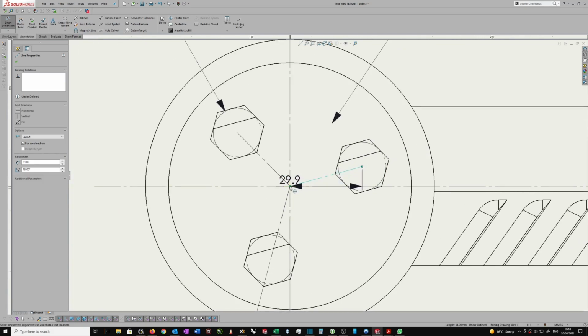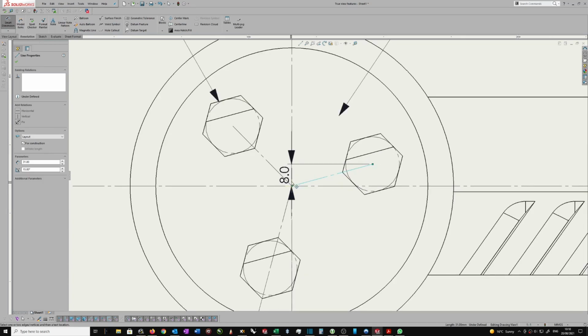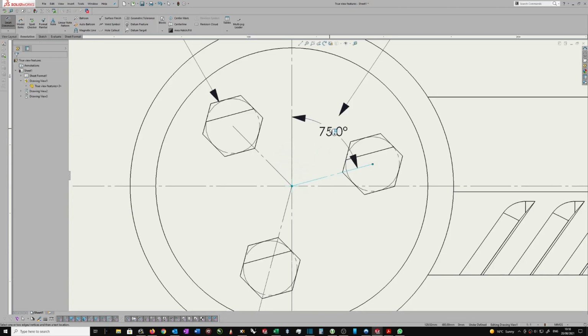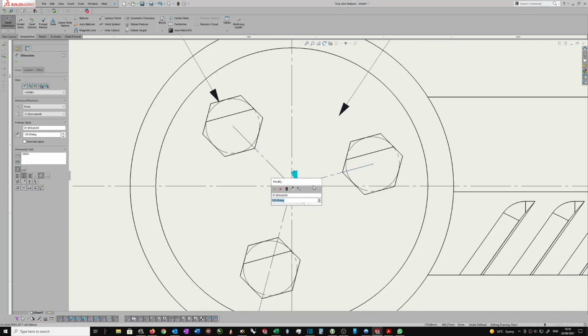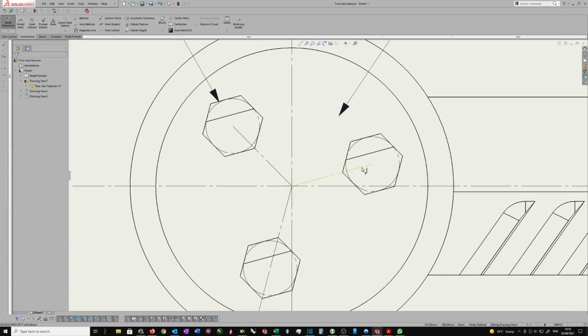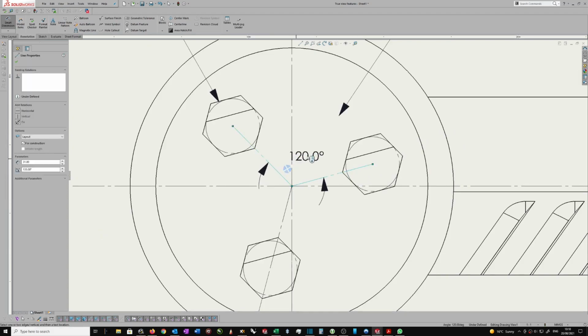So if you select the center point, if you select it on either of the axes, it'll dimension to that axis. So this is the vertical axis that I'm selecting, so it'll dimension to the vertical axis. That's why it won't give me this line here. If I select to the horizontal axis, let's do that again. Right, so go from there, and I'm selecting the horizontal axis of that center mark, so it'll give me the horizontal one. What I want to do is I want to dimension from that line to this line, and all I do is select the 2.